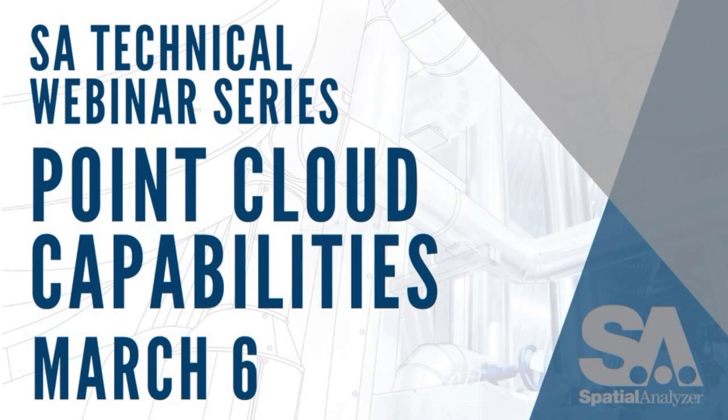It's going to prompt me to select my cylindrical face. Come in here and select that face, and then select clouds. So now we do have a cloud and our constructed cylinder. If you select on that relationship, you can then see the deviations from our nominal.